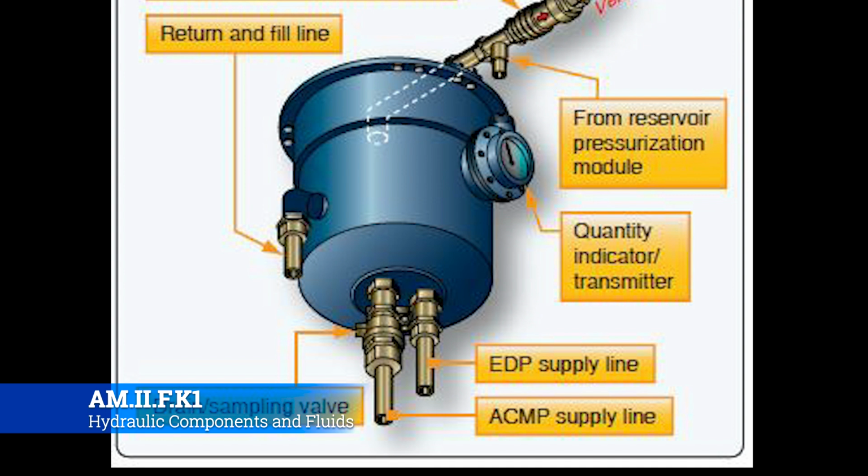Now, that doesn't replace the sight glass, because there's always the possibility of an instrumentation error between the transducer and the cockpit. It could be any number of things. It could be corrosion on the connectors, a broken wire, or just a bad transducer, any type of thing that could cause some sort of stray voltage or deviation in the transmission of that information. And so nothing's going to really surpass literally putting human eyeballs on it, but you can't do that in flight. So you have something to let you know, hey, this is what our hydraulic quantity is.